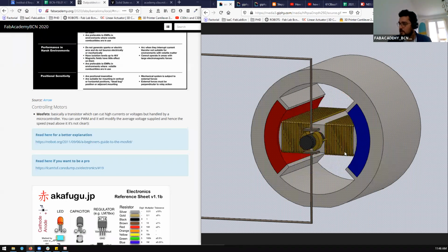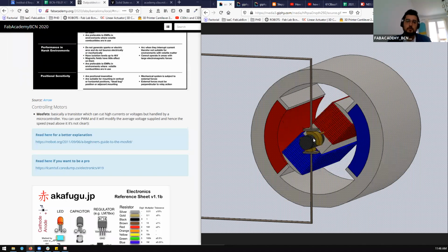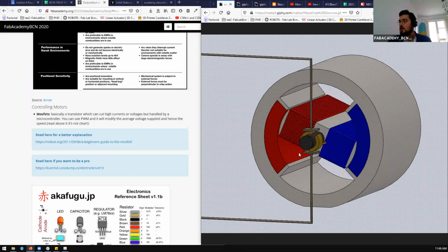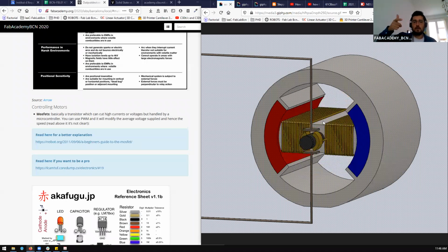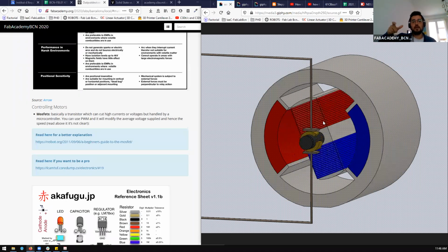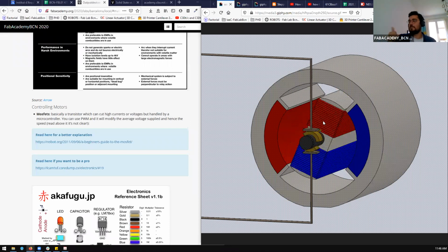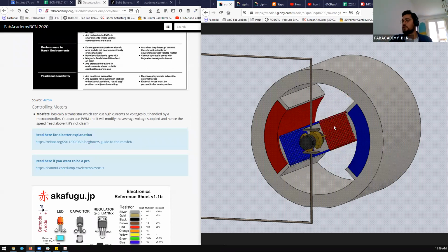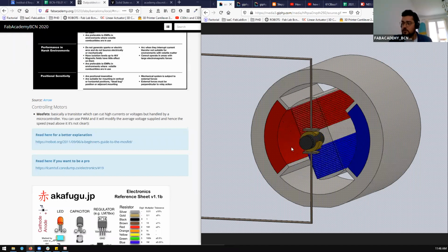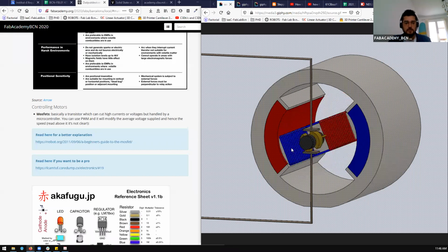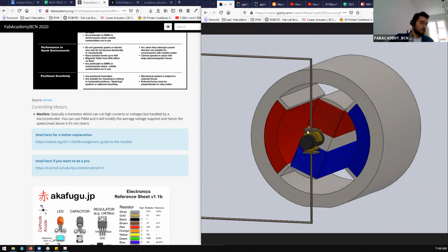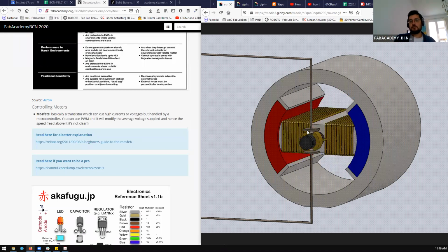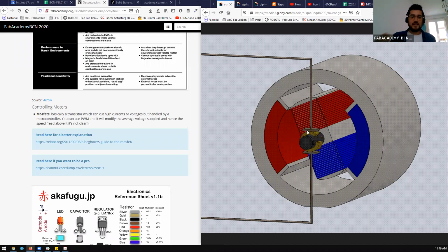All the time, for example, you see red, blue, red, blue, red, because by changing the location, it automatically changes the direction of the coil. So that allows a permanent change in the direction on the same coil, without having to actually change the battery terminals or the power supply terminals. You do this internally. This kind of motor is what we know as brushed, because these pads are metallic brushes, the same, on a small scale, as the one that you use for cleaning your floor, because they are more or less the same.